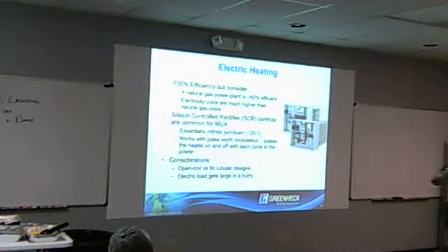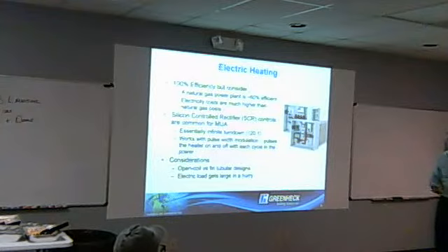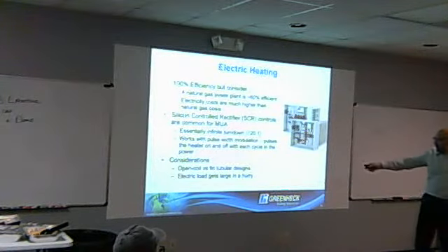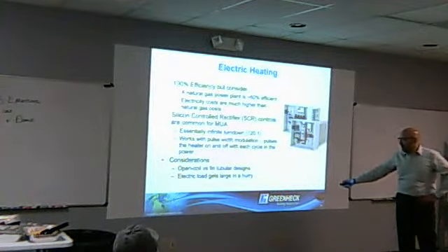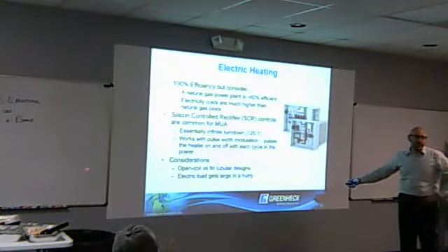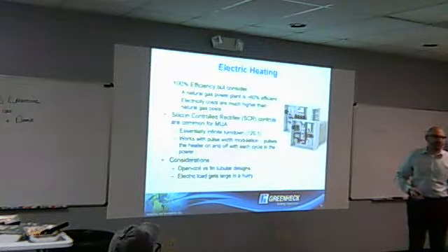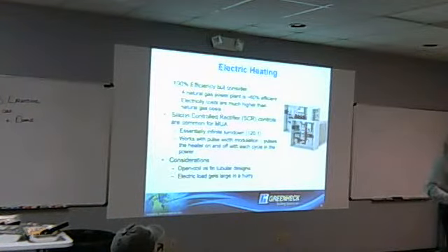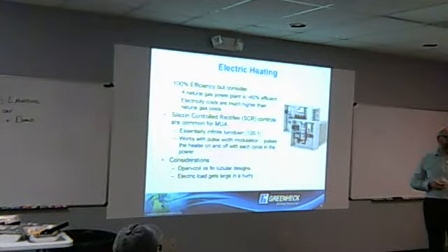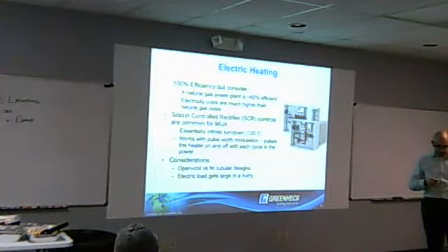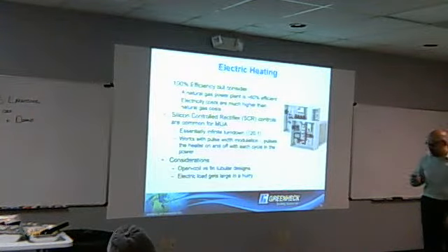Open coil, this is fin tubular, I mentioned that. What we do watch is sometimes somebody says, well, I have this large amount of outside air, if we go electric, now that load on the electrical panel and wiring gets pretty big, and they're like, oh, shoot, I didn't realize it was going to be X amps. Then they tell you they want cooling. Well, you're back to the electric heat, because you're going to need it for the cooling. Excuse me, when it comes to the compressors, right?